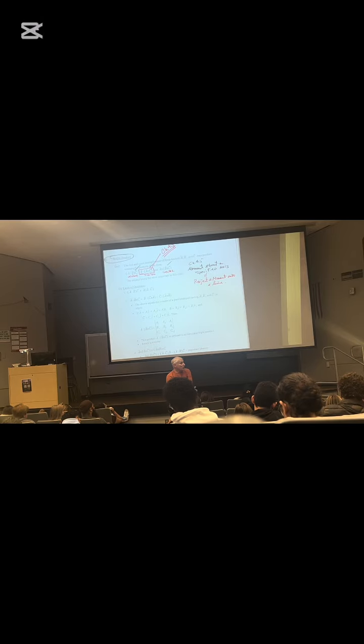So really, what you're doing in chapter 4, section 5, you're going to say it's A dot B cross C. A is going to be the unit vector of the line, B is going to be the R, and C is going to be the F. That is projection of a moment onto a line. That is all that's in this section.